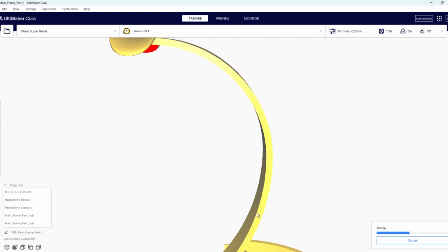Imagine my mouse is the nozzle, extruding the filament. The nozzle is going to be going up like this, all cool, up, up, up, up, up. And then once it reaches here, the filament that it extrudes out is just going to fall. When it's here, it has something to build off of, which is the filament beneath it. So it's building, building, building, but then when it gets here, there's nothing underneath it. So it just falls, and that's why we have supports.